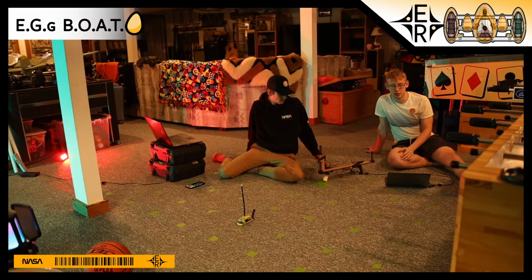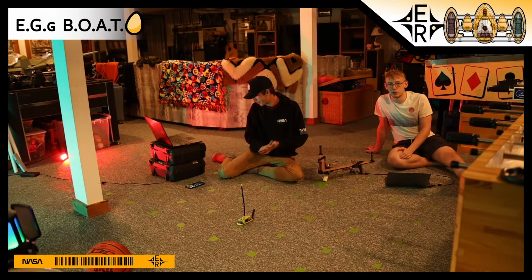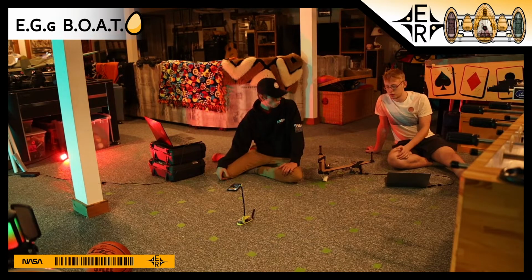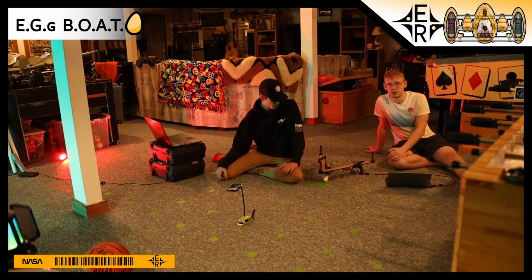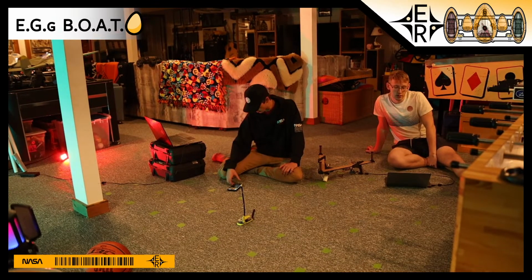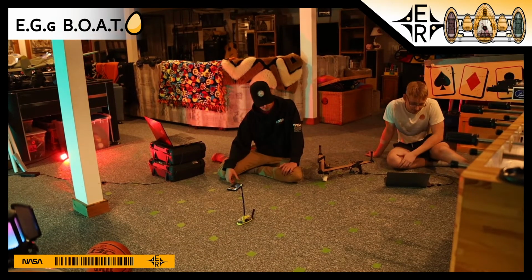So really what we're getting are just solid 0 or 1 outputs before it receives the signal, which makes sense because we're outputting from the digital logic circuitry. And when it's not running, the 2 outputs will be opposite, I guess: one will be 0, one will be 3.3. When we convert those constant signals into the averager, it's not really doing anything, it just leaves it at 0 and 3.3, and that's why we're getting about these values.